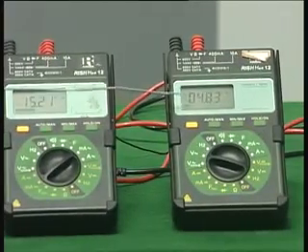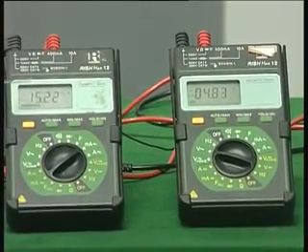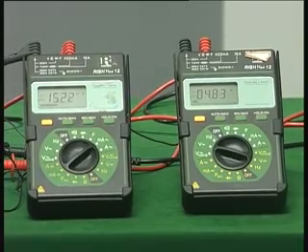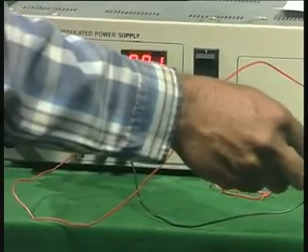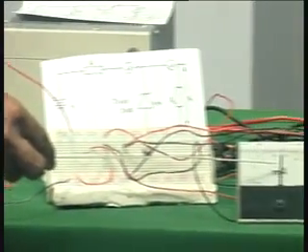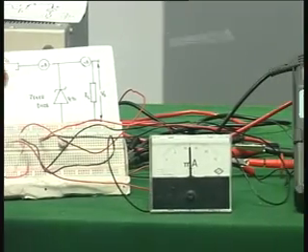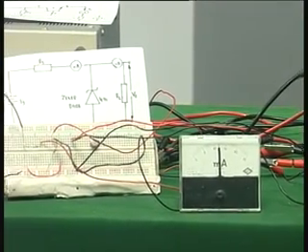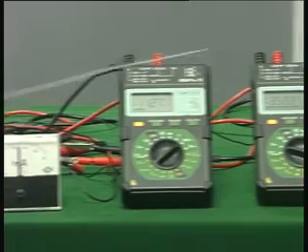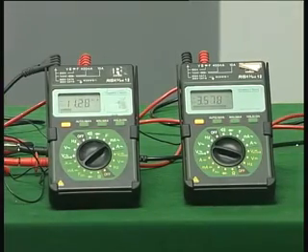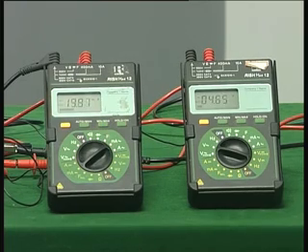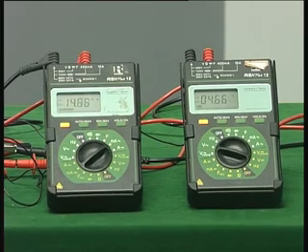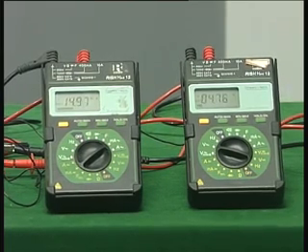You can see the voltage is around 4.8. The load current is around 15 milliamperes. Now if I decrease it a little bit, you can see the series current also decreases, right. If I come below 4.6, this voltage across the load, the Zener, is also decreasing. If I bring it above some 6 or 7 volts, you would find, for example, it is about 7 volts.